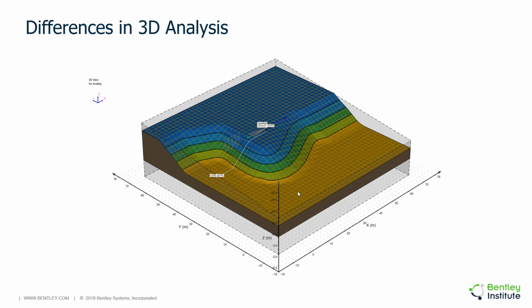So I like this model. This was proposed by a Japanese researcher, and it really just illustrates a very simple topology, but one that is very difficult to actually analyze in 2D because you don't know ahead of time what direction the slip might take. And the topology really dictates that this should ideally be a 3D analysis, because it's hard to pick any particular slice through this model that doesn't have a 3D topology effect. So it's very easily demonstrated on simple analyses that these models are difficult to solve with a standard traditional 2D profile approach, and yet they're quite common. This is the typical slope that we would find in most municipal design and city planning, how we lay out our cities.